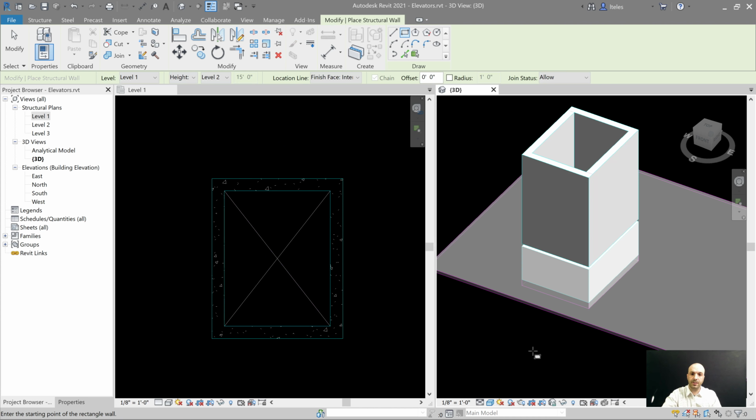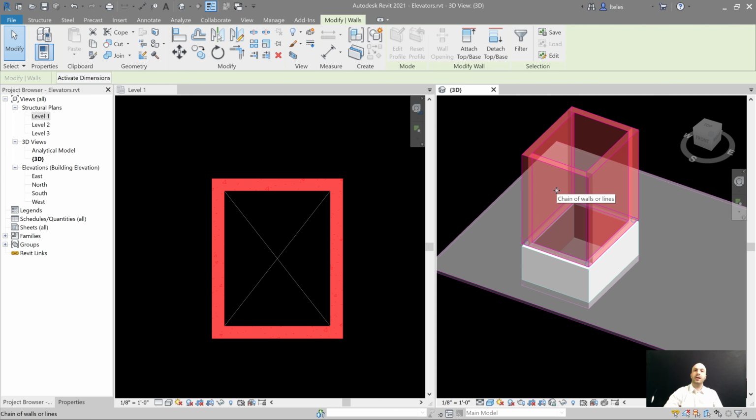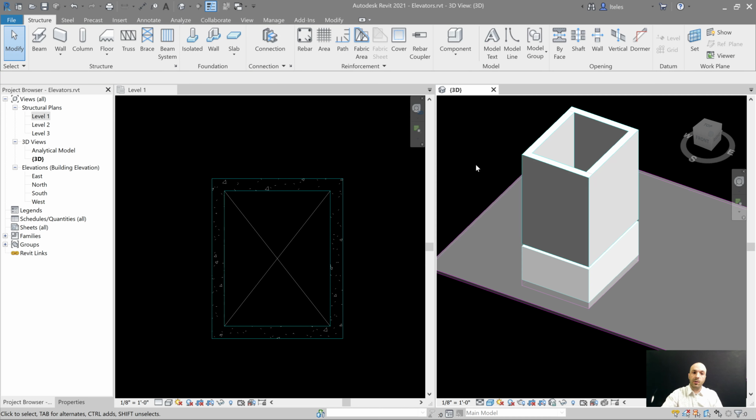All right. Now let's hit escape twice, and in 3D you can hover over one wall, tab till they highlight, select, and you can go over the same workflow for attachments. Let's attach the bottom, the base, to this floor, and then you don't have to worry about anything else. Now, a nice little tip that you need to be mindful that exists is the locking tool.